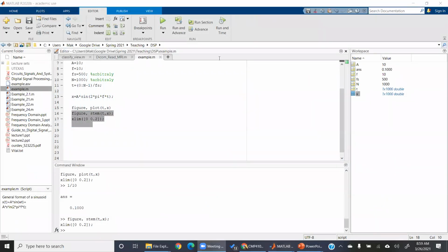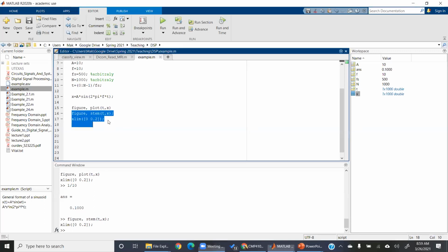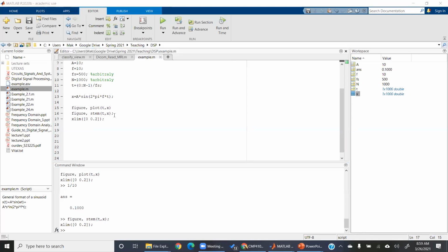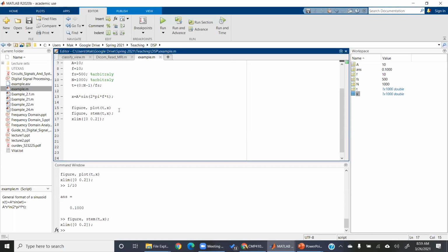My question is, how do we know the exact sampling frequency? To me, it looks like trial and error. No, it's not trial and error. Nyquist already tells you that you need to use at least twice. But what I've just shown you is that at least twice is the bare minimum.